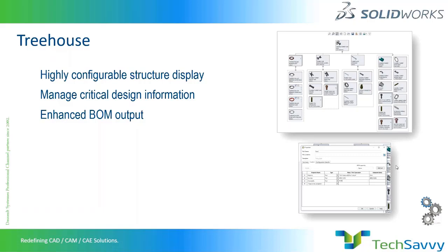So Treehouse inside SolidWorks will basically enhance all those areas. Now when you present or send your data to those departments who are not technical, they can understand what the main assemblies are, what components are used inside that main assembly, how many components there are, along with the picture, name, and part number. Previously we could only get that update through part properties. Now in SolidWorks 2019 there is bidirectionality, in which I can update the part properties and send it back inside the Treehouse update.